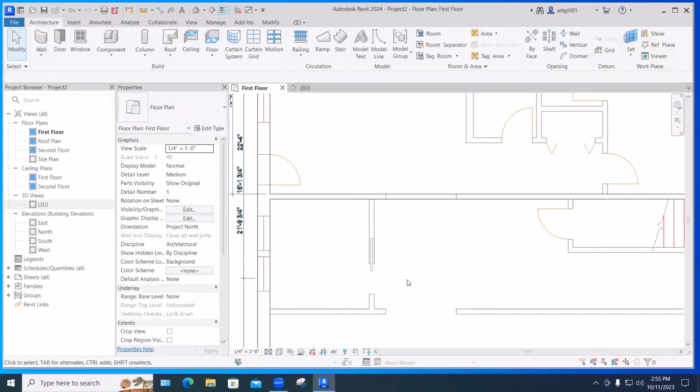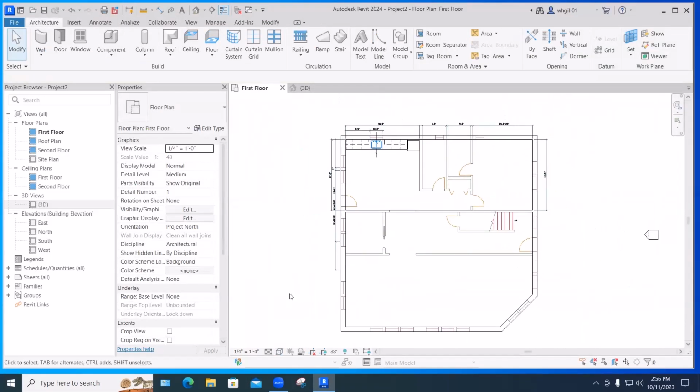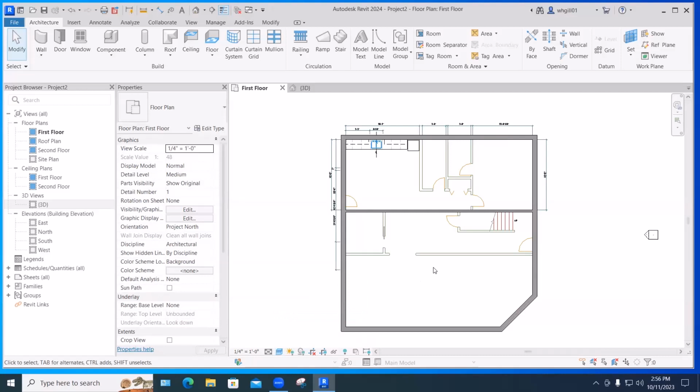Okay. Bingo. We'll go over it in much more detail on Monday, the different viewing options and visual styles in Revit. But a helpful one right now, just to keep track of where you've put walls and where you haven't, is on this icon right here, right next to detail level: visual styles. If we change that to shaded, then we can see where we've actually created our walls compared to the ones that are underlying it. We're probably going to turn that off when we start placing the doors and things so we can see the jamb lines.